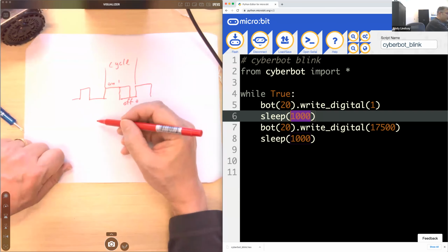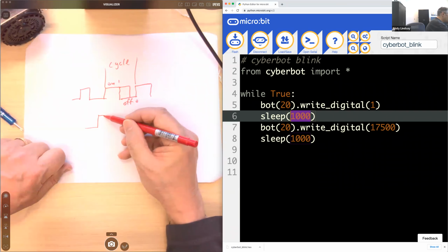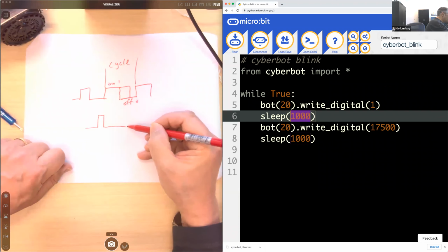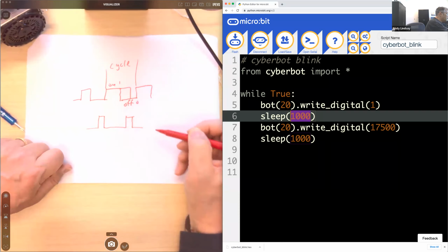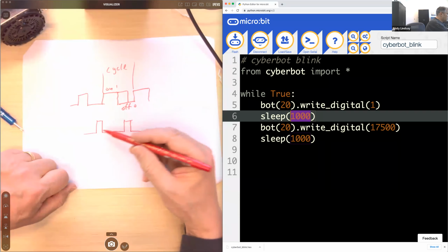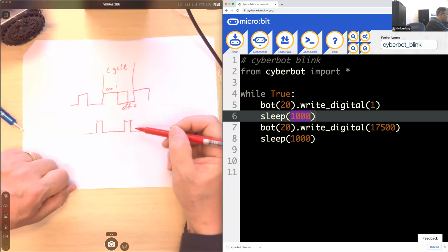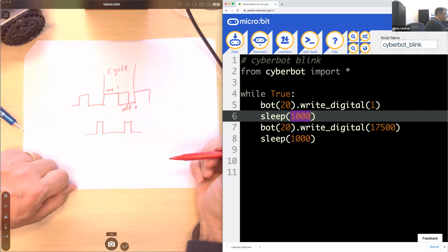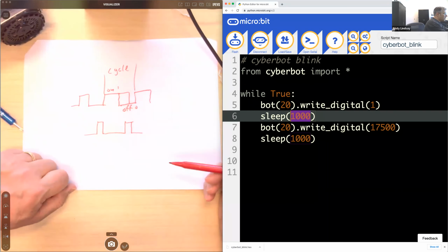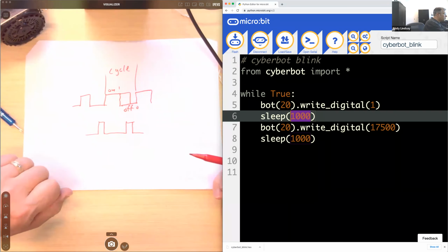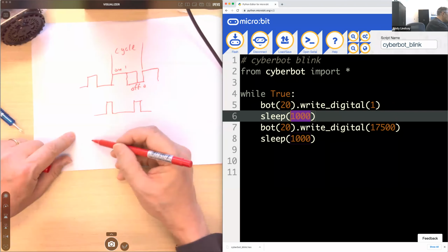If you instead gave it maybe an on time, and these are happening very rapidly, like maybe 50 times a second or 1,000 times a second. It varies with the motor that's controlled, but this would make it go maybe 20% of full speed. And then of course, on half the time, off half the time would be 50% of full speed. So that's a typical motor control signal.